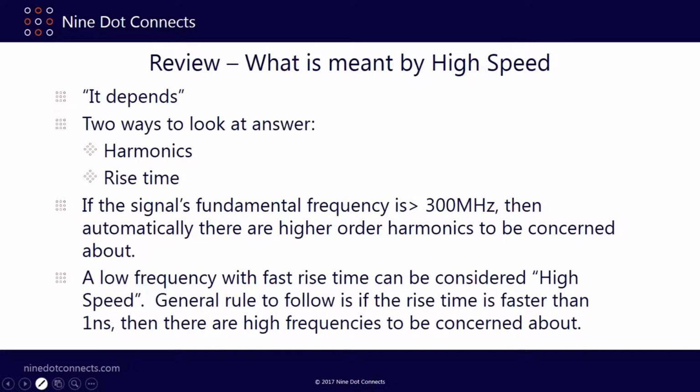A low frequency with a fast rise time can be considered high speed. And the general rule to follow is that if the rise time is faster than 1 nanosecond, then there are definitely high frequencies to be concerned about.